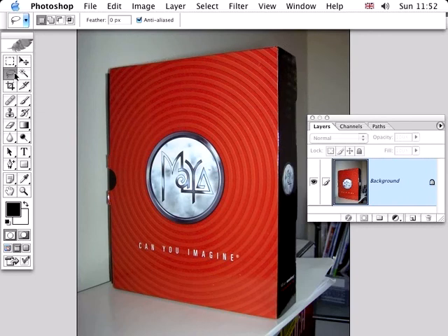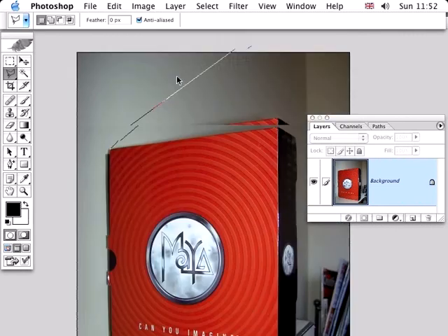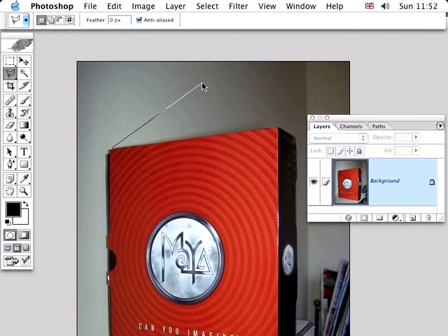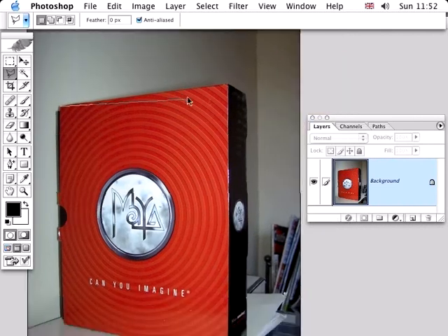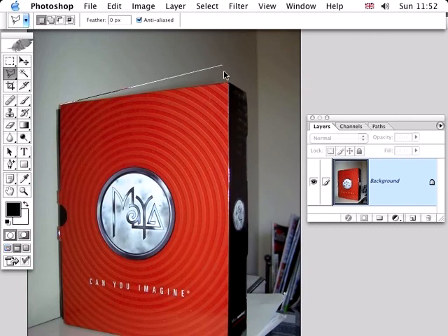Really, it's going to be a bit of a nightmare. But the Polygonal Lasso tool is much better because it's like a kind of elasticated tool. You can start at a point like the corner here, and as you draw, I'm letting go of the mouse, and it's not making the selection, it's not snapping back, it's just quite happily waiting for me to make the next selection here.